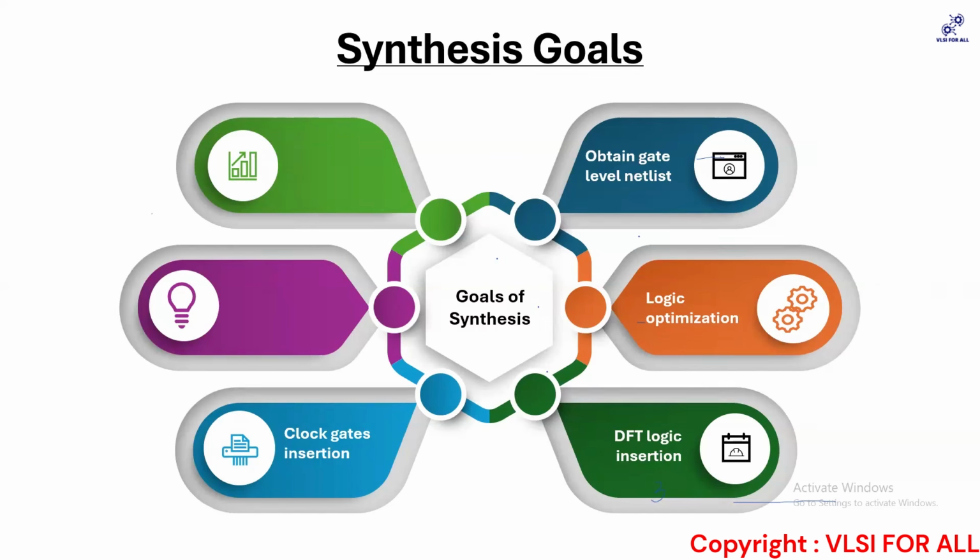Okay, but at the initial stage, when you're giving it a try and starting the synthesis, you don't know where the person who receives the netlist will place the memory in the design, or where he will place this analog logic, this PLL logic. So the placement can change. Now if you have a very hard-constrained DEF, there is something the tool cannot optimize, and it will again result in that zigzag manner. So you have to enable it at your PNR stage as well.